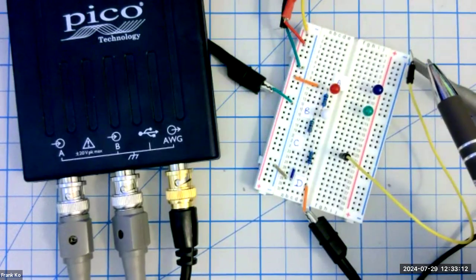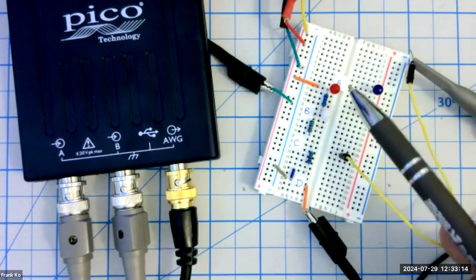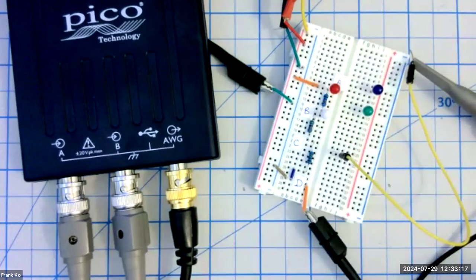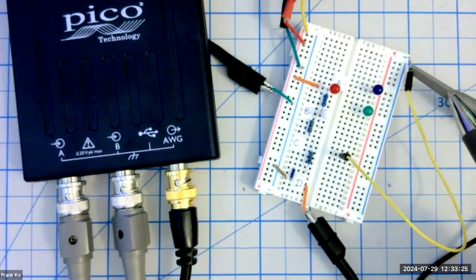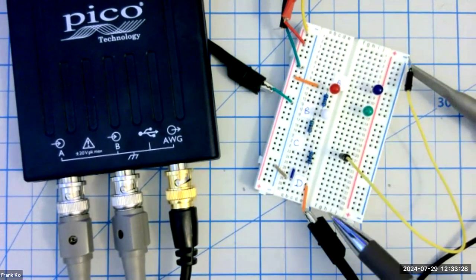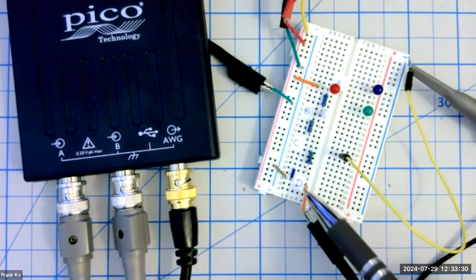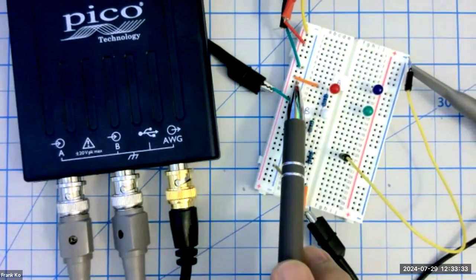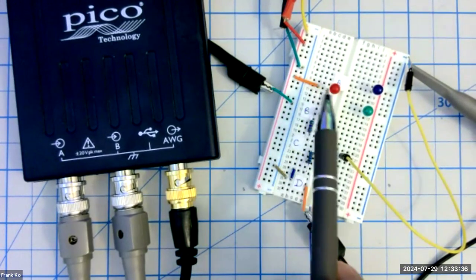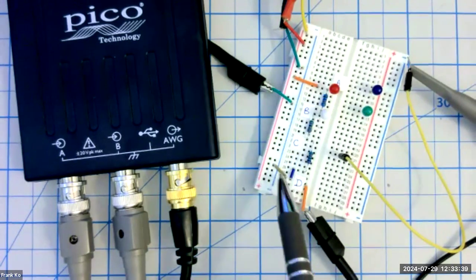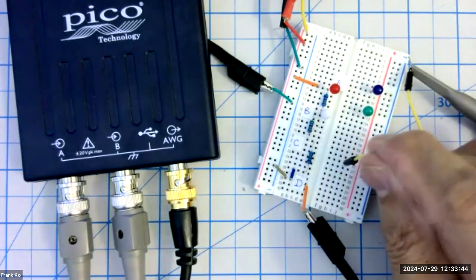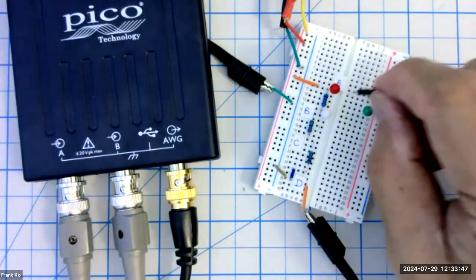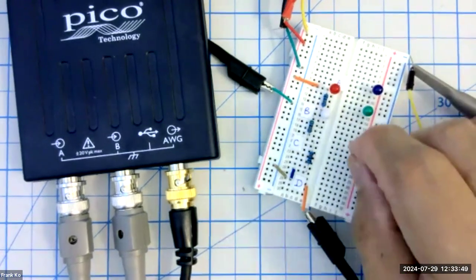So this is what I'm going to be able to compare and see, if I go to point A, point B, point C, whether our predictions match our actual measurements on the PicoScope. The ground for the channel B oscope lead to the PicoScope is grounded here at point D. So we have this loaded presently. This is the jumper wire from the red rail to the first resistor, through the string of resistors down to here to the blue rail. So this is set up ready to go. And then I will use this handy dandy wire jumper to place where I want at different places in order to make measurements.